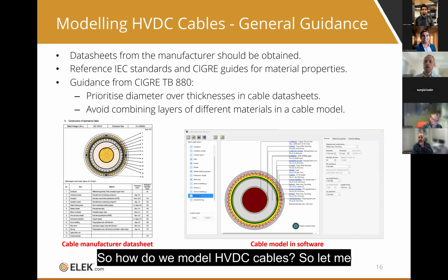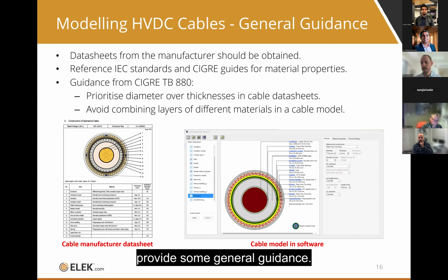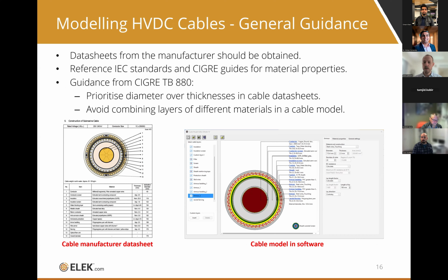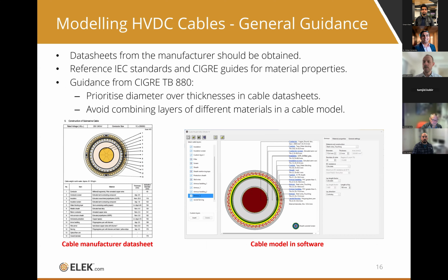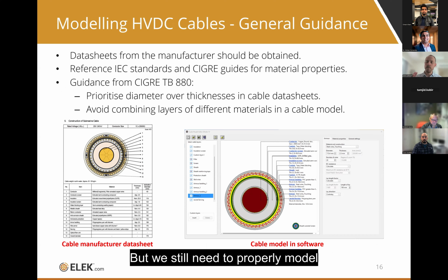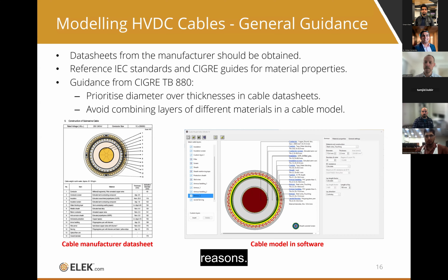So how do we model HVDC cables? Let me provide some general guidance. It's actually much simpler to model the cable itself. They're generally much simpler cables. They will almost always involve an armor layer. But we still need to properly model these cables for thermal and electrical reasons.